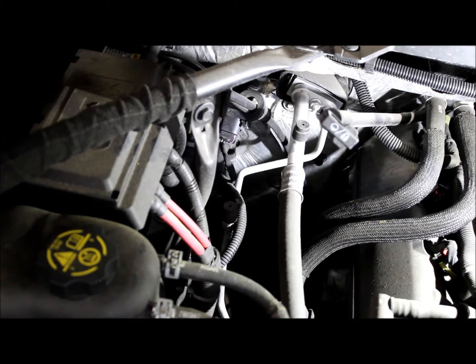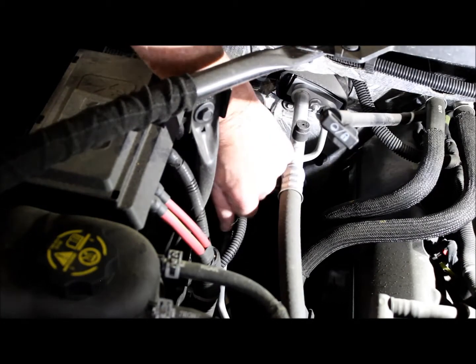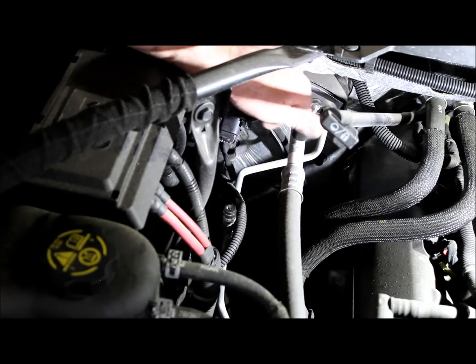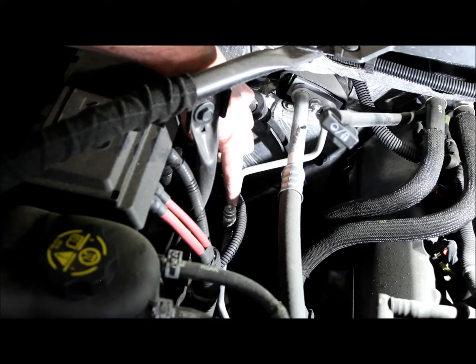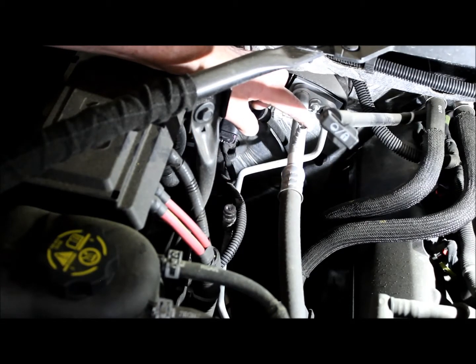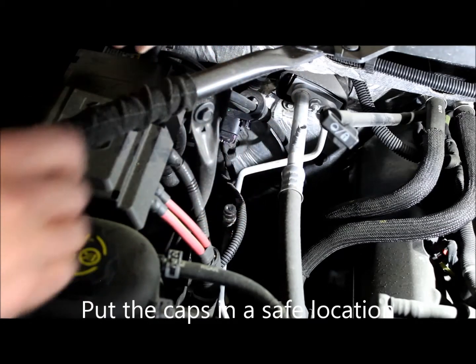Before we can hook up our service equipment, we need to identify our service ports. We've got a high and a low side service port. The ports are here and here. Now when I take the protective cap off, you'll notice the low side port is smaller than the high side port. That's probably the easiest way to remember it. Big equals high side, small equals low side. You don't want to lose these caps, they keep dirt out of the valves.